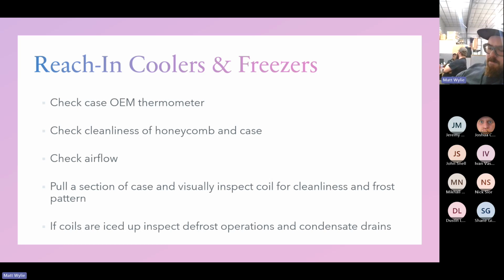So, and correct me if I'm wrong, anybody, but clear ice, or like the melty ice, can be humidity issues or them leaving the door open on the walk-in. And I would assume that's not overnight. That's been going on for weeks, right? Yeah, and they'll tell you, oh, that just happened this morning.